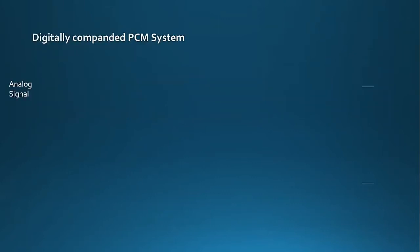So let's look at the digitally companded PCM system, wherein the digital companding is very evident. Say for example, we have an analog input signal. It could be a voice, digital process, or data. Then it passes through a bandpass filter. Our bandpass filter limits the frequency of our analog signal. It only passes a certain frequency that is within its range.